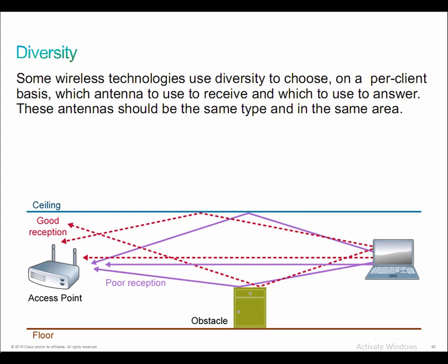Multipath propagation is, like I said, a problem that occurs on indoor wireless networks. One way to solve the problem is to move the client away from the zone where reflection or refraction affects the signal. The problem of where to locate the AP is usually solved by permanently mounting it in a particular location, meaning that you always have predictable outcomes. You always understand what kind of service is being provided by that access point. In the case of diversity, though, we use two antennas. We place them one wavelength away from each other, and that's where that distance comes into play.